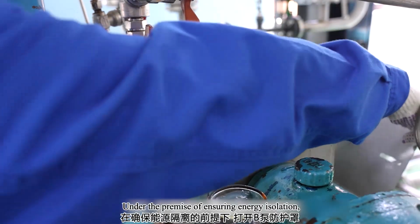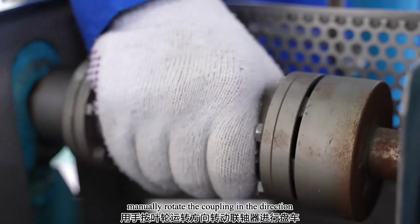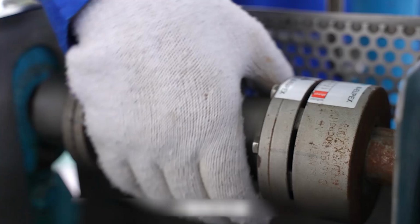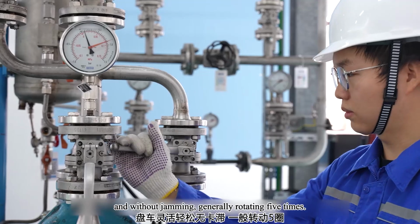Under the premise of ensuring energy isolation, open the protective cover of pump B. Manually rotate the coupling in the direction of the impeller rotation for alignment check, ensuring it rotates smoothly and without jamming, generally rotating 5 times.